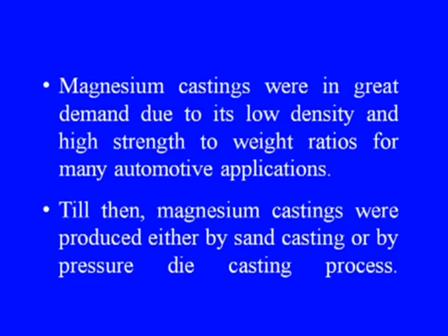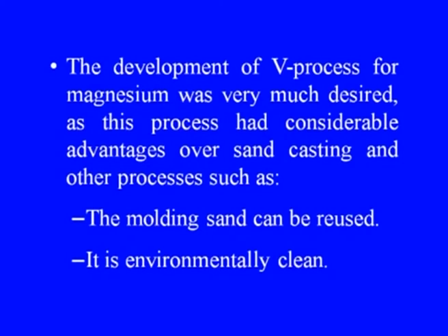Magnesium castings were, however, in great demand due to its low density and high strength to weight ratio, and this material is highly sought after in the automobile sector particularly, because low weight and high strength materials are required, which magnesium and its alloys can offer. Till then, magnesium castings were produced either by sand casting or by pressure die casting process. The development of V process for magnesium was therefore very much desired,